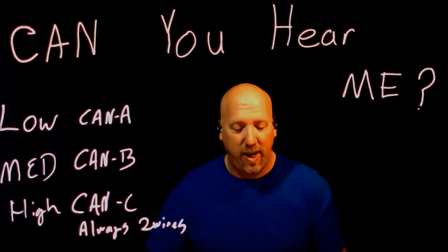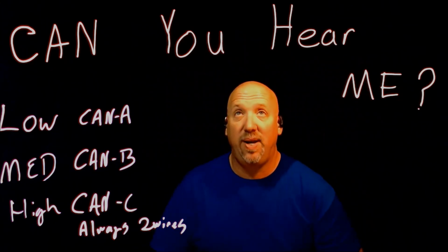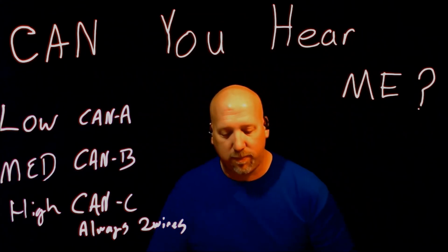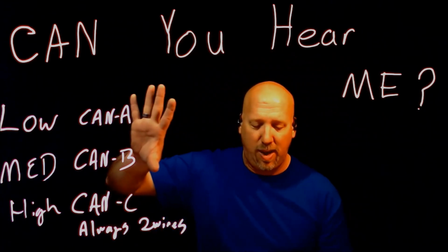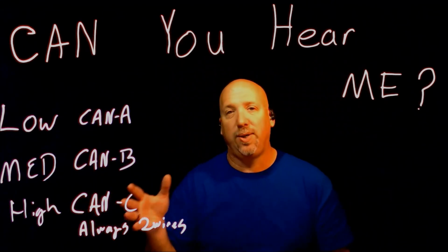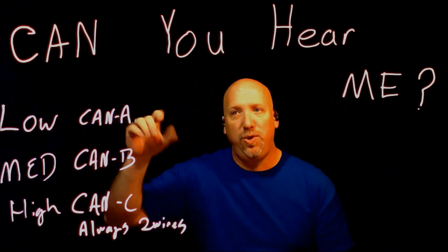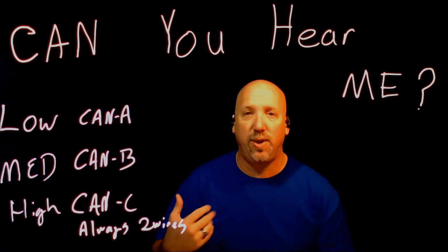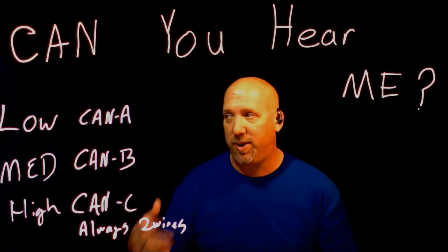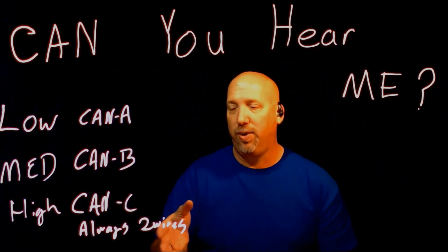More stability is gained because, in the strategy building the CAN protocol, the modules identify themselves by priority. When one sends a high priority signal, the other modules stop talking. It's kind of like in your classroom when all of a sudden the teacher walks in. Most of the other conversations die down so the instructor or professor can speak. The instructor has the priority message, and then all the other modules, or all the other students, stop talking.